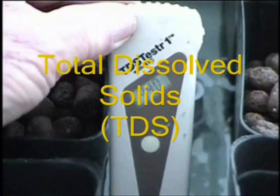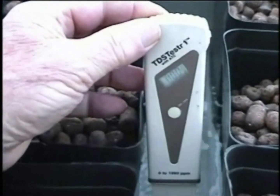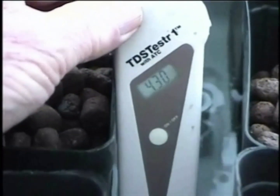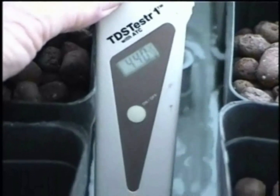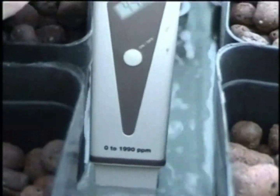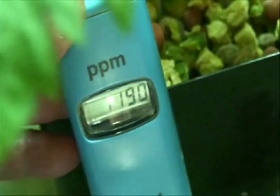The TDS meter measures the total dissolved solids, which represents the concentration of dissolved minerals in the nutrient solution. The concentration is indicated as parts per million, or ppm. Very basically, the whole thing is accomplished by an electrical current passing between two electrodes submerged in the nutrient solution.